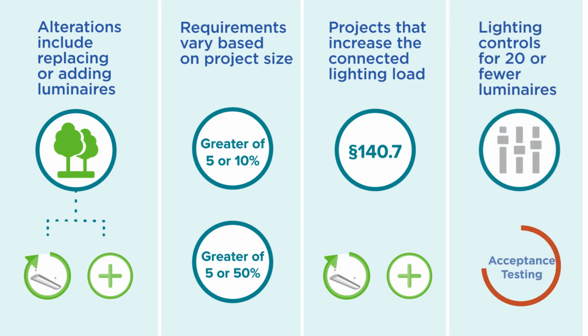Any outdoor project that adds lighting controls to control 20 or fewer luminaires for the entire project without increasing connected lighting load is exempt from acceptance testing.